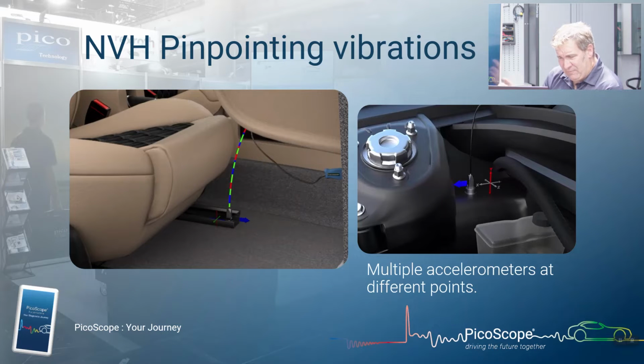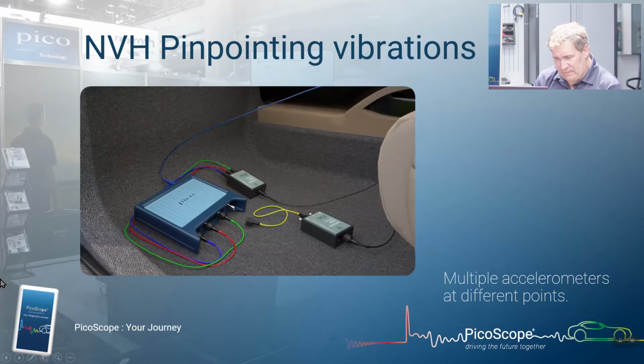So there we are on the seat frame. We've got our 3 axes of measurement. And now we're going to put a second accelerometer. We're going to put this under the bonnet, nice secure location, and then we're going to run the same test again. So let's have a look at this.